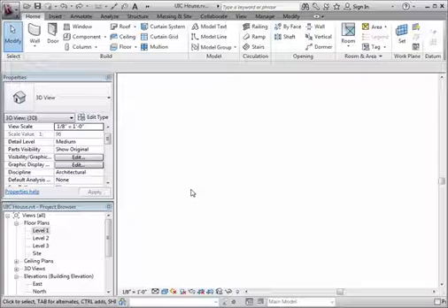You could set up a user file, central file relationship, which is probably a good idea. The reason you would get fired if you worked in the central file is that if there's only one file, imagine this: there are thousands of hours of work put into that one file, and if that one file is destroyed or corrupted or ruined, then that's a tremendous amount of money and investment that goes to waste. So that's what's nice about the user file, central file setup: you have a group of temporary files, any of which could be converted into a central file at any time. It's essentially a bunch of backup plans in case the central file gets corrupted. So it's important for you to understand that I just saved my central file that I'm now working in, which is probably not the best way to work.